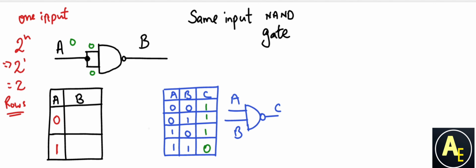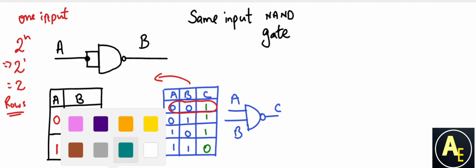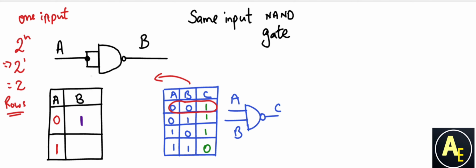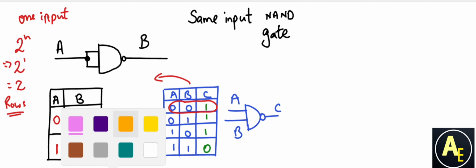Here we can see that for a NAND gate, 2 low inputs give us a high output. It would therefore make sense for B, our output for the shared input, to also be high or 1. We look at the last row of our NAND truth table as well, where if 2 inputs are high, then our output will be low.